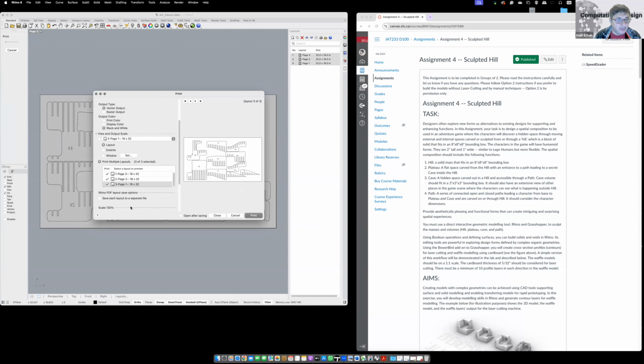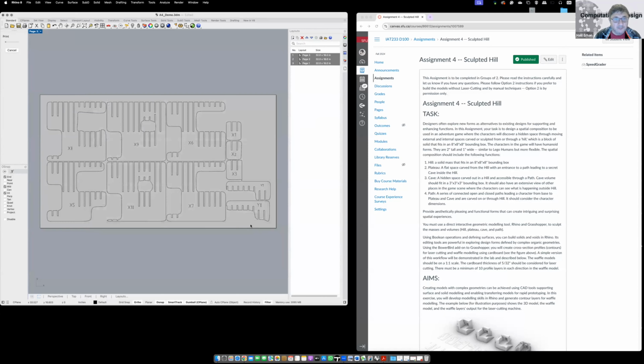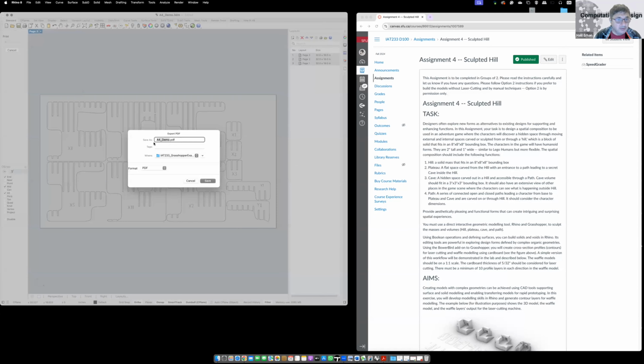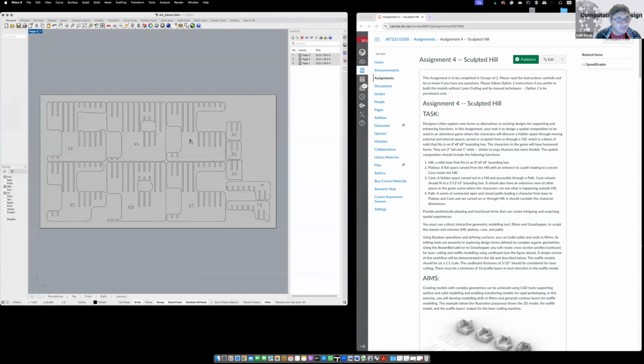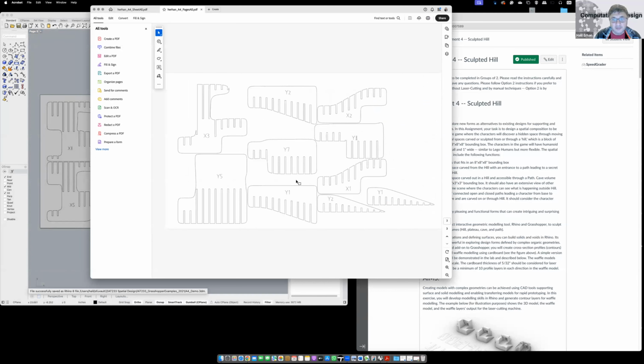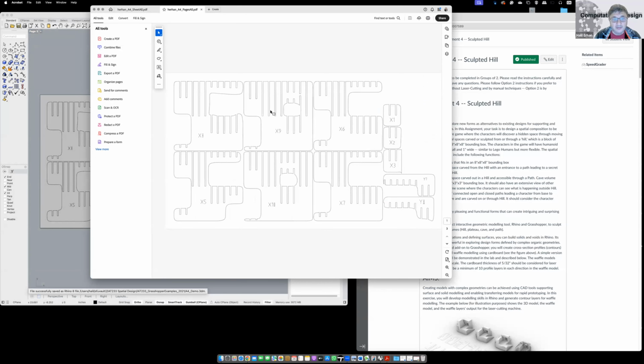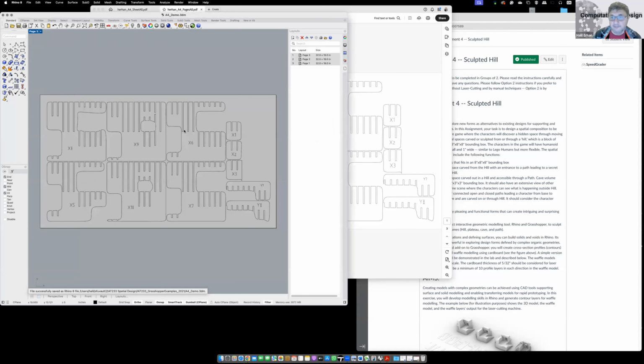It's set to black and white. Scaling is 1 to 1. Remember, 1 inch to 1 inch. Check this one definitely. Otherwise, it's not going to work. Then print. Once you say print, I will print it as a demo and save this. Don't forget to save your files. These are the pages I just printed. Then you can upload this file to Canvas for our solid space technicians to laser cut them.